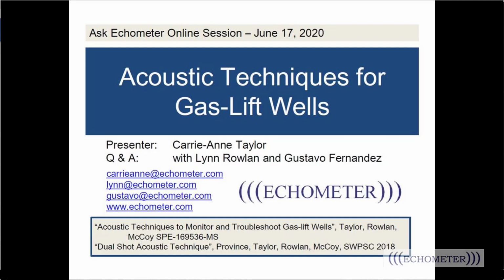You know, that's a good question, but it's really somewhat depth dependent, because if you have, let's say the chart says for a casing pressure of 85 psi, you need to use 400 psi charge pressure. Well, that's only true if the well's 5,000 foot deep. If the well's 10,000 foot deep, you probably need to use, maybe 800 pounds of pressure. So it's not only a chart of differential pressure, but it's a chart for casing pressure and charge pressure, but it also is depth related. So, and then also restriction related.